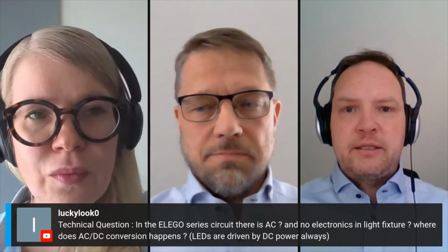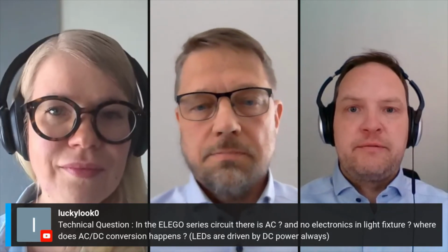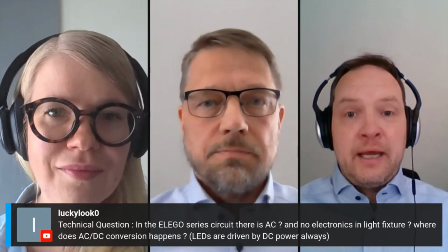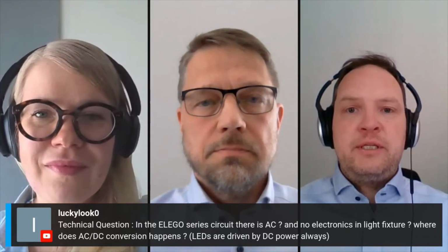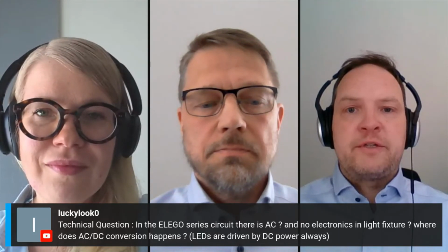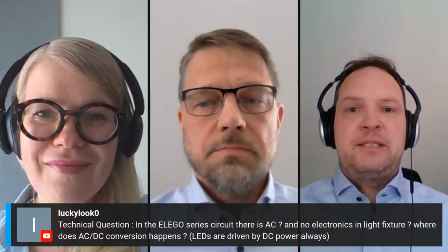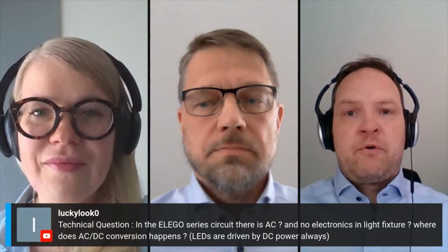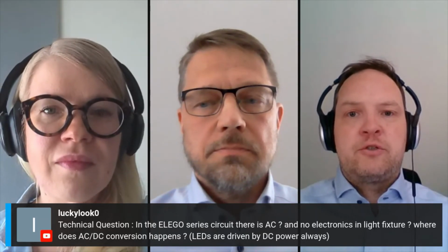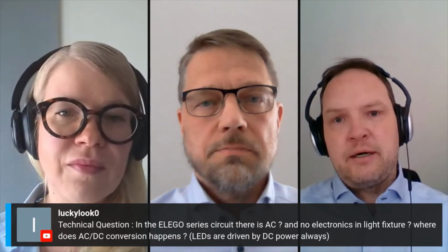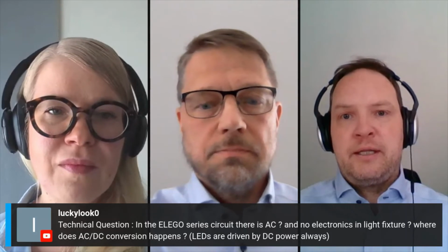Yes, so correct. It's AC, of course, because of the transformers, it has to get through the inductive devices. The LED is a DC component. So the AC to DC conversion or transformation happens within the LED bulb. So the LED bulb is AC driven. Therefore, there's no need for anything active or any transformations between the CCR and the LED bulb. So it's all AC between the CCR and the LED bulb.